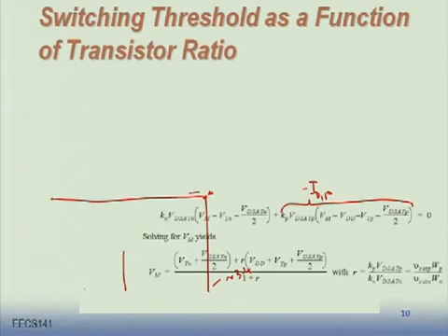It is governed somewhat by the mobility ratio. No, it is not really by the mobility ratios. It is primarily governed by the mobilities and VD sats. That's what comes out of this equation. Regarding your earlier question, yes, you're essentially right. The wider the NMOS, the more current that NMOS transistor conducts, so it will intersect the appropriate PMOS curves earlier.